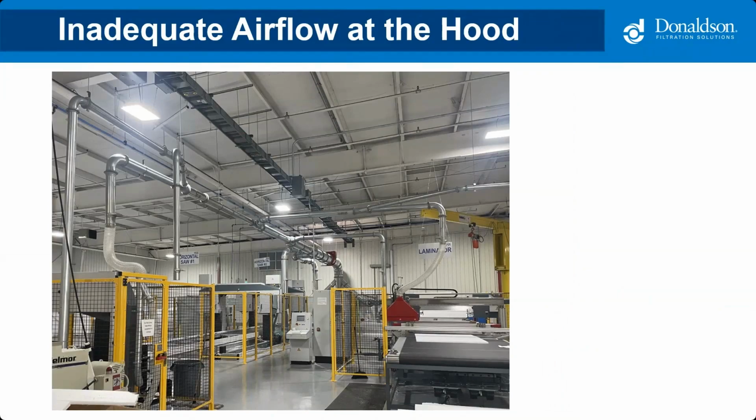Another big issue I see is inadequate airflow at the hood. In this picture, there's multiple pickup points, which is pretty common with an engineered system. Each hood is designed individually for a specific airflow. We're going to cover this more extensively in next month's webinar on duct design.